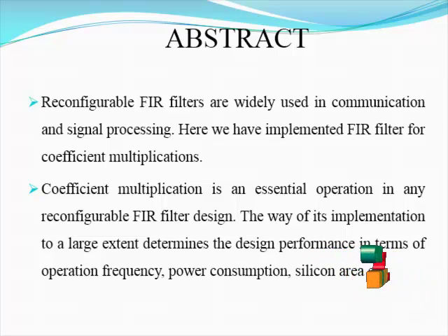Complying with the principles of the CSE algorithm, various reconfigurable architectures were also developed. A structure called combination sharing multiplier employs a precomputer to generate some common partial products. Subsequently, multiplication of the coefficients can be carried out simply by performing shift and add operations on those common partial products. A binary CSE method was aimed at reducing the number of those adders actually performing redundant binary common suboperations.